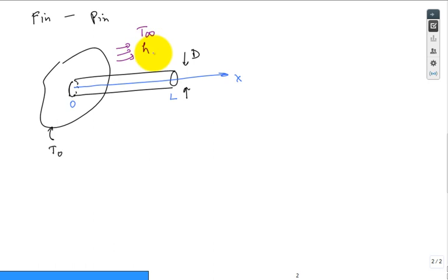All right, we want to find the governing differential equation in order to solve it with the boundary conditions for the temperature at any location X as you go out. We're solving for one-dimensional heat transfer. Our boundary condition number 1 is that the temperature at 0 is equal to the temperature of the base, or T naught, either one. Let me call this base temperature TB instead of T naught.